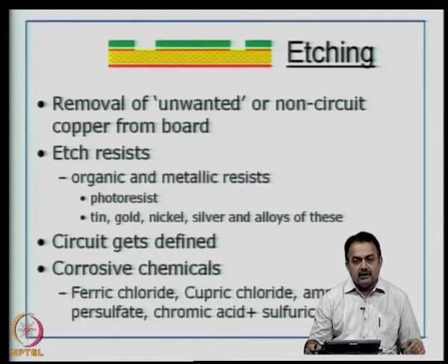So, nickel is known as an undercoat or a very basic essential requirement if you want to plate gold on copper. The thickness of nickel can be around 3 to 5 microns, and gold can be about a micron or less than 1 micron.